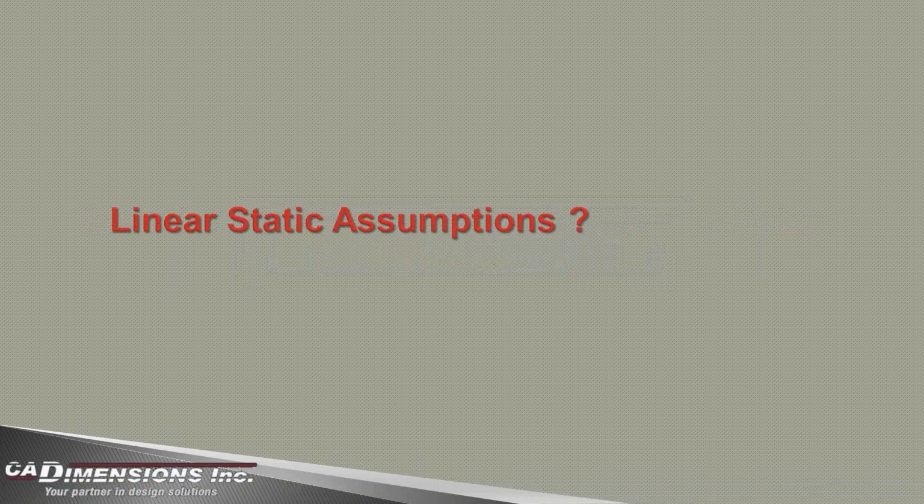We wanted to understand today how and when I can use SOLIDWORKS Premium to run an analysis. And in order to do that, you need to understand what makes a problem linear and static. So there are some assumptions about what we're doing that make it linear and static. Let's go through those real quick.